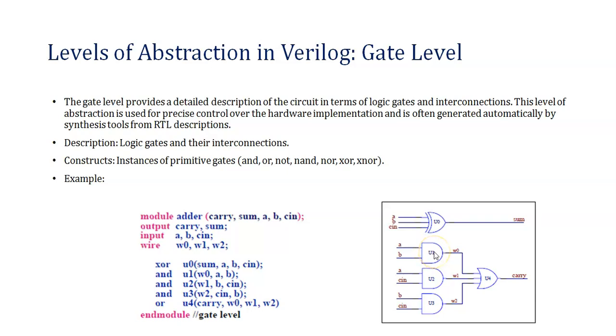So here, as you know, whenever you are solving the equation for a full adder, you will be getting something like sum equal to A XOR B XOR C. Here the same is mentioned, the diagram related to that XOR gate is there, A, B, C in are the inputs and you will be getting sum. And for carry the structure is like this: A and B, or A and C, or B and C in. This is the carry. So this structure is known to you.